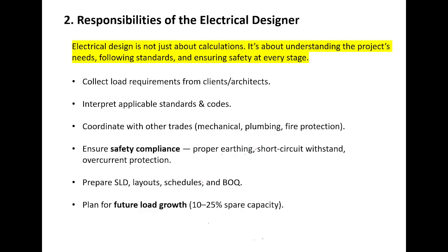Okay, so this is very important. Suppose you are working on IEC codes, so as per IEC, the voltage drop should not be greater than 3%. You cannot take a value more than 3%, because if you are working as per IEC, you should comply with that.